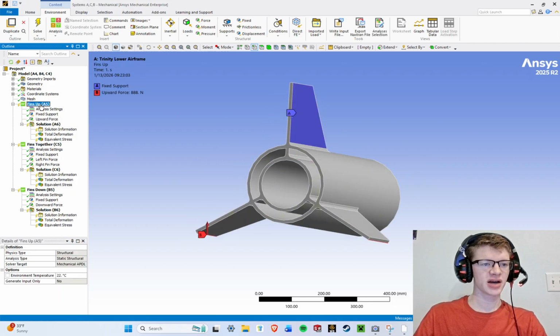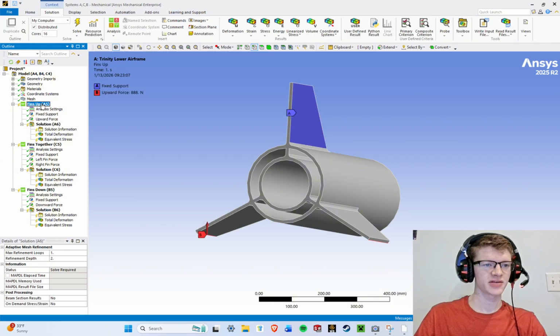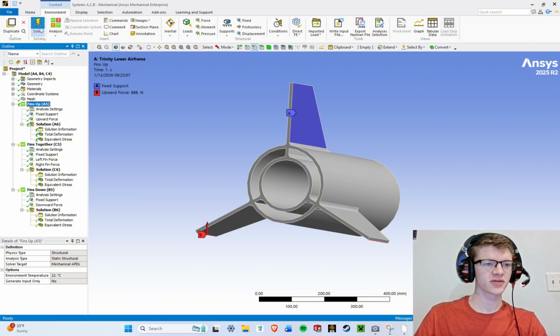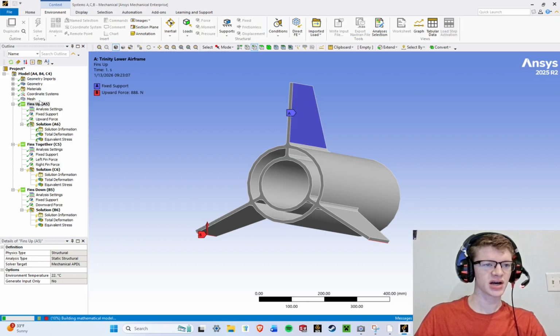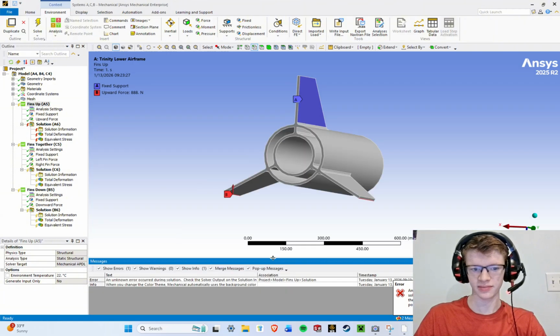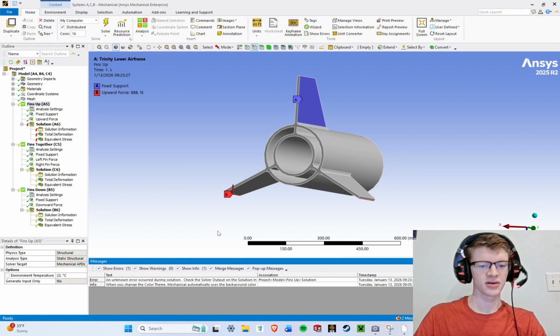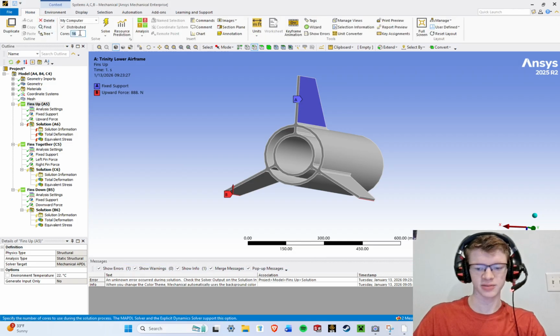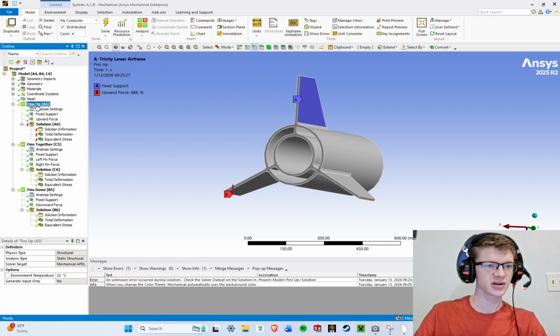If we click fins up, or something under fins up, and we click solve, it's going to show a green lightning bolt for all of the things under fins up. And it is going to solve everything, including an item under the tree that we selected. Oh dear. An unknown error has occurred. Well, let's troubleshoot. I'm going to reduce my cores to 4 and see if that solves it.